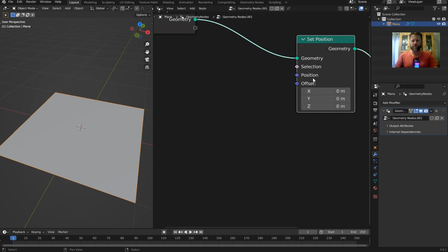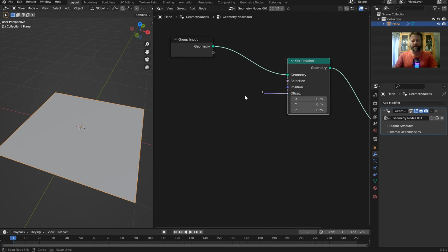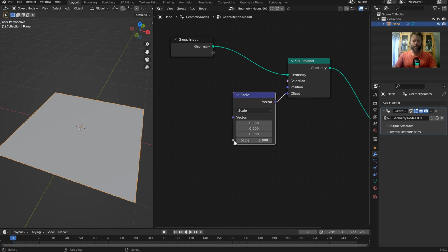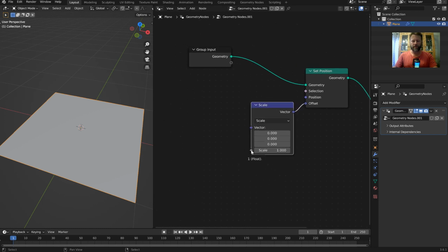so we can have a nice procedural little landscape. So what we're going to do is create an offset, and the offset is going to be very simple. We can just type in scale, for vector math scale. Okay, now what we want is to displace this on the normals straight up, because this is going to be like real ground geometry.